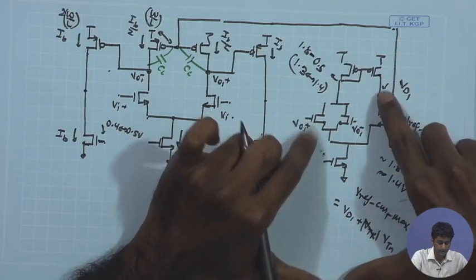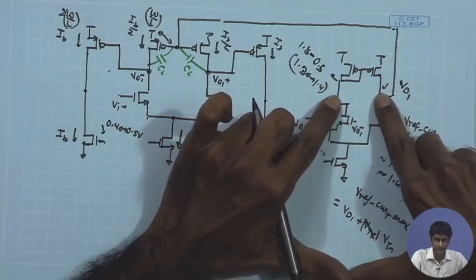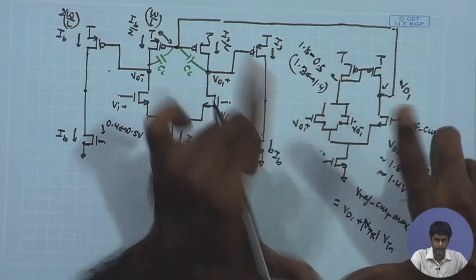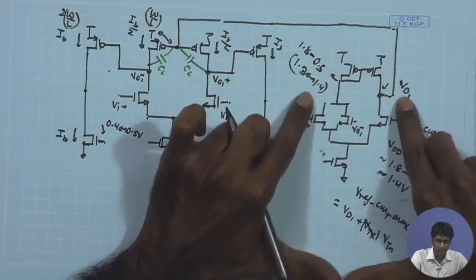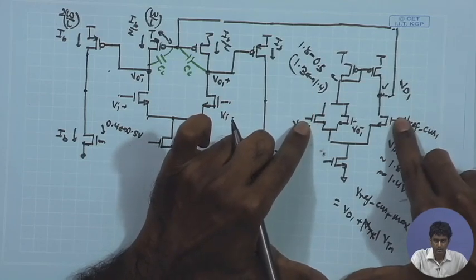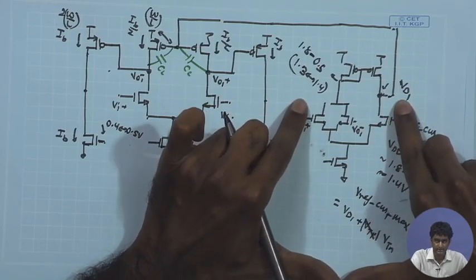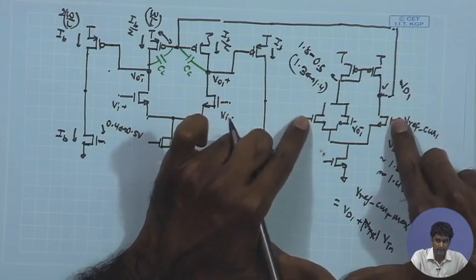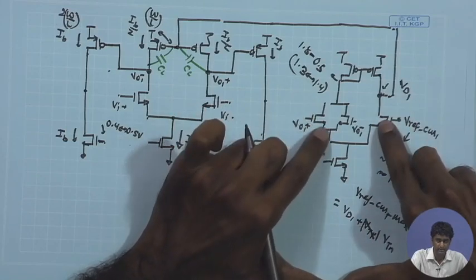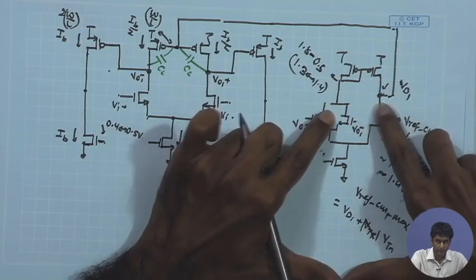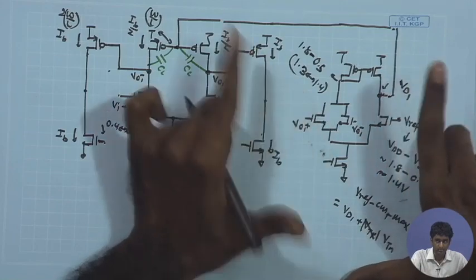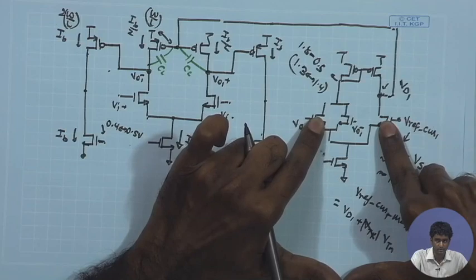from the maximum side this drain potential is being clamped with the help of the direct connected MOSFET, and for that particular drain potential I am just seeing what is the maximum allowed VCM ref that you can put. If you go on increasing the gate potential further and further, what is the maximum gate potential that you can have while keeping this transistor in saturation? That is going to be the drain potential plus Vt. Beyond that, the transistor over here will be entering into triode region.